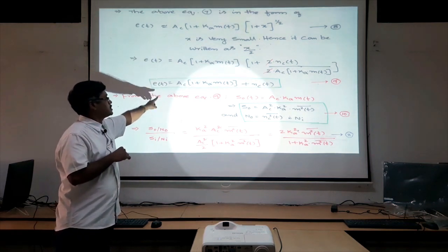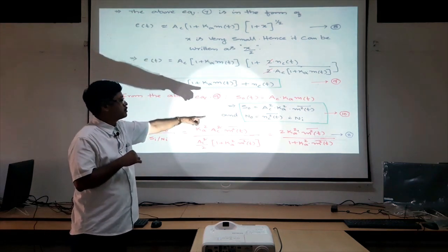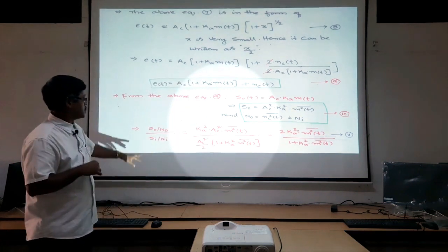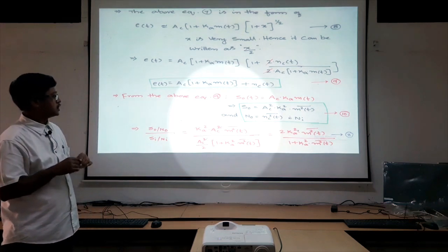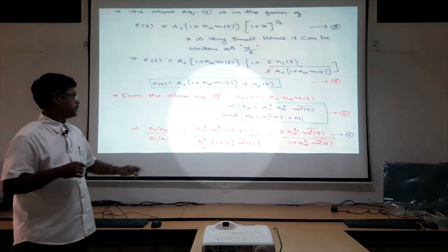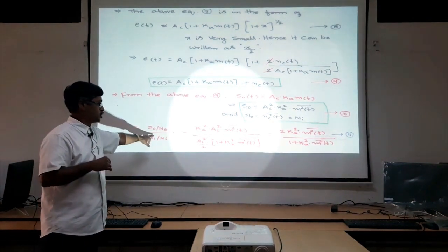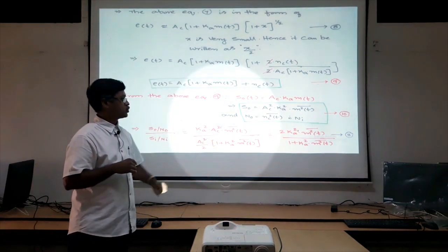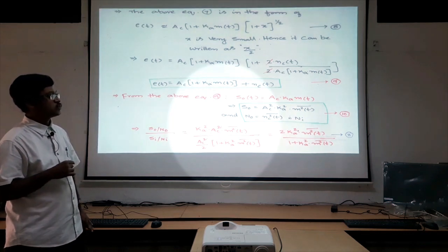Now from equation 9, try to define the signal power and noise power as So and No. From So and No, try to define the output signal to noise ratio. Now, if we consider the overall signal to noise ratio, which is defined as the figure of merit, that is output signal to noise ratio to input signal to noise ratio, after simplification it gives 2 times Ka square m square t bar divided by 1 plus Ka square m square t bar.